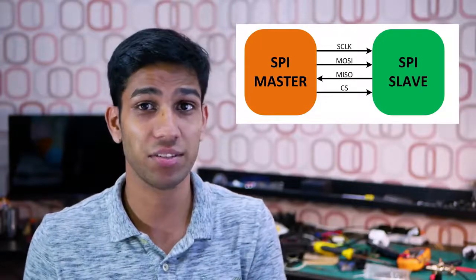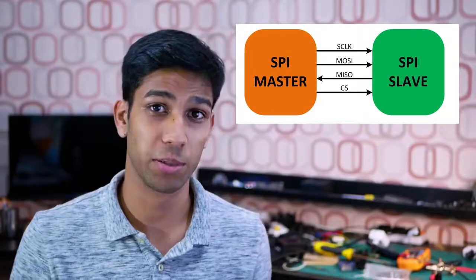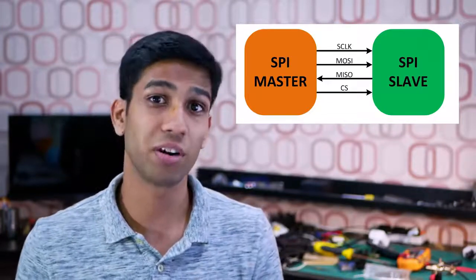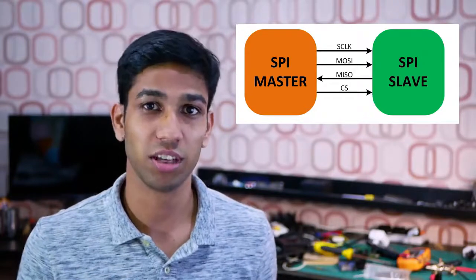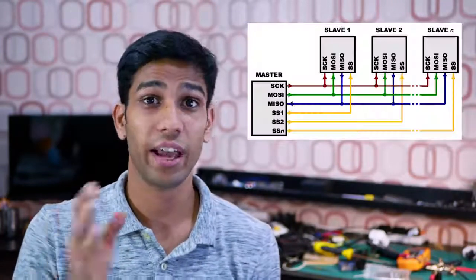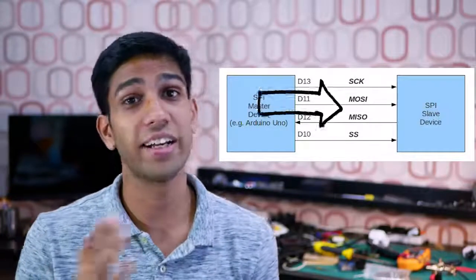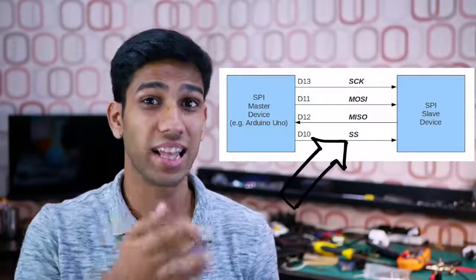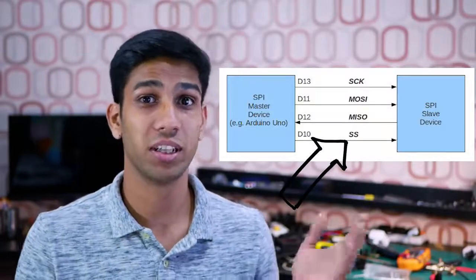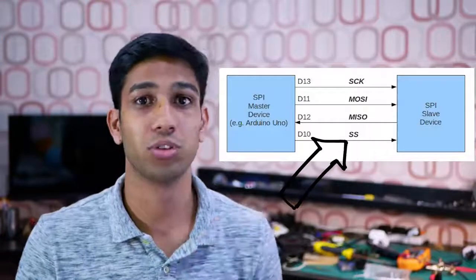Just like I2C, SPI supports masters and slaves. Now masters are typically a microcontroller such as Arduinos or Raspberry Pis, and slaves are usually a peripheral such as the SD card, sensors, or shift registers in this case. Unlike I2C, however, SPI only supports one master. SPI also uses separate clock and data lines to facilitate communication, and it also has a slave select line for the device, like a microcontroller, to decide which slave or peripheral it wants to communicate with.